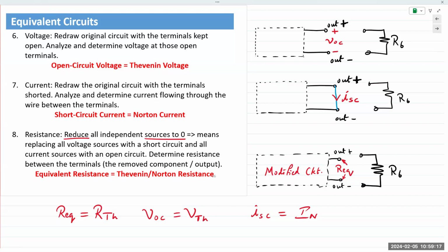No, that applies to all three values that you determine at the end. So we can use Ohm's law as verification at the end. Obviously, if you're doing this in real life, we can find two quantities and find the third, which is what we do for RTH. In the end, it turns out that all circuits are not reducible down to one single resistance. Most circuits are complicated. We cannot find REQ that way. So the only way to find Thevenin resistance is to find the Thevenin voltage, find the Norton current, and then apply Ohm's law. V over I would give you the Thevenin resistance.